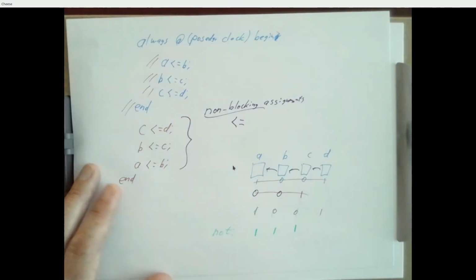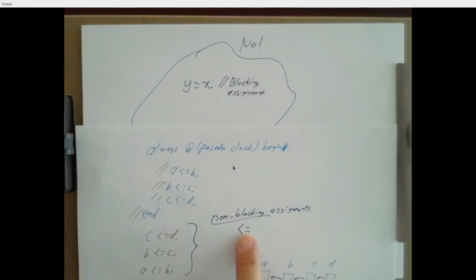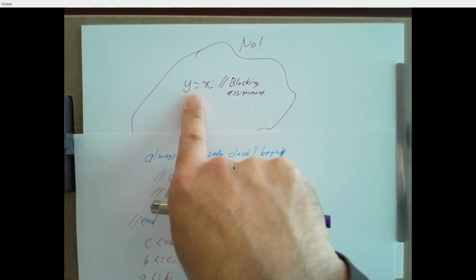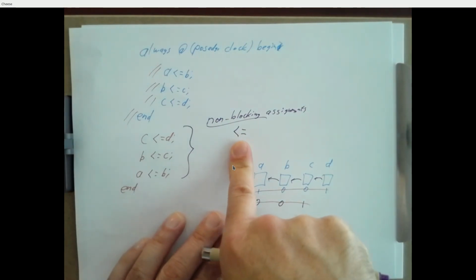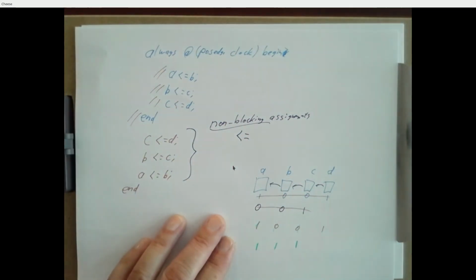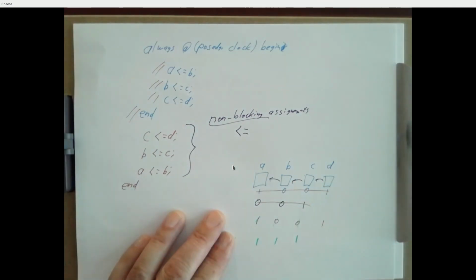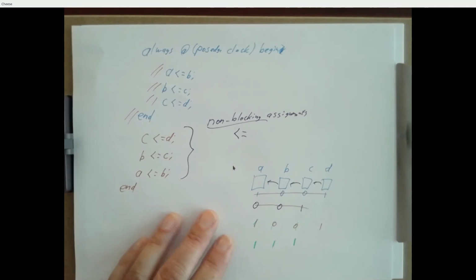And for what we're doing in here, you don't need to use these blocking assignment statements, and I suggest you totally avoid them. Okay? But I mention them just because if you forget to put the less than sign, and you do one of these, you won't get a compile error. But if you're getting weird behavior, go back and make sure that you're using non-blockings. So for an assign statement, we assign y equals x. Inside an always block, we say y less than equals x, right? The little arrow symbol. So that's a gotcha to keep an eye out for.